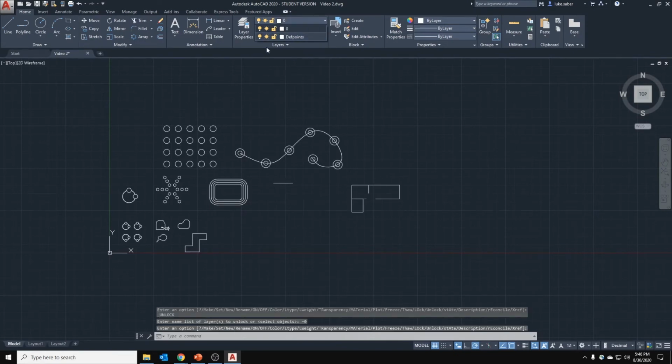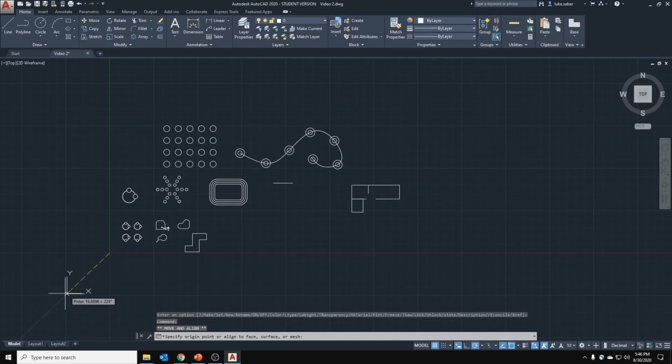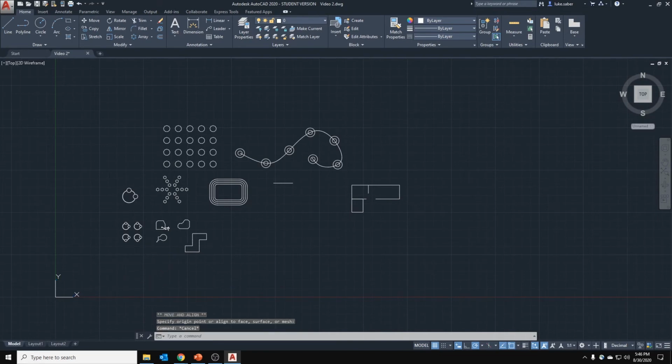You can do all that, but what's valuable is all of the stuff we have here is based on lines, right? So these lines, you can make them thick lines, you can make them dotted or dashed with patterns, you can also make them different colors, but maybe you don't want all of your lines to be the same kind of thing here, so how do you change that? Well, layers is your answer. So before I do this, I don't like how this is right here, so quick tip, you can actually just move the origin by grabbing it and dragging it, which is pretty cool.